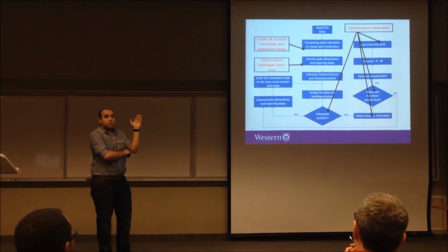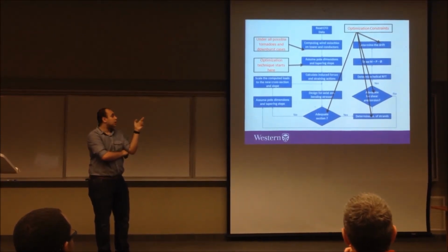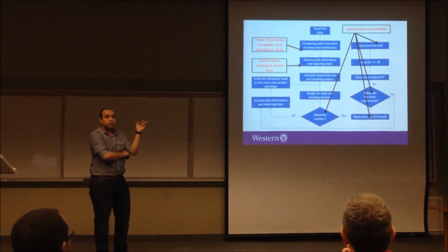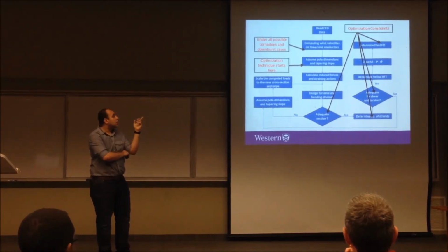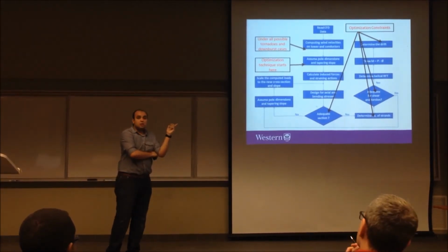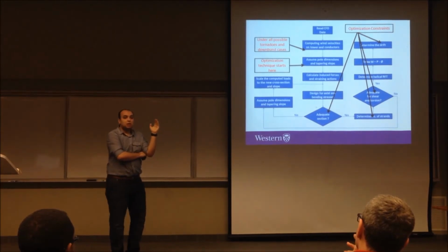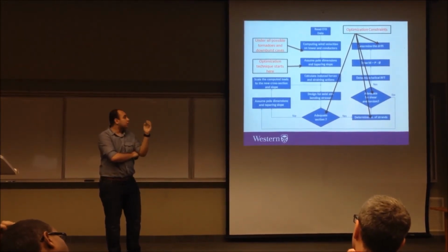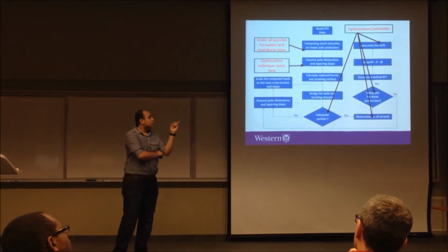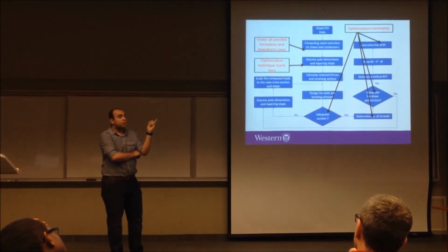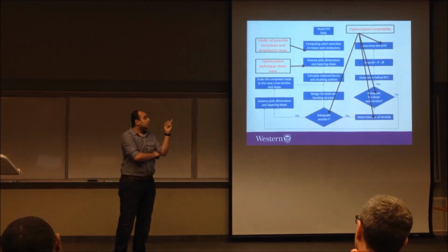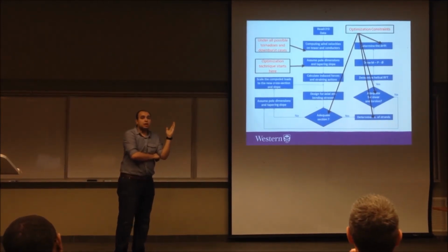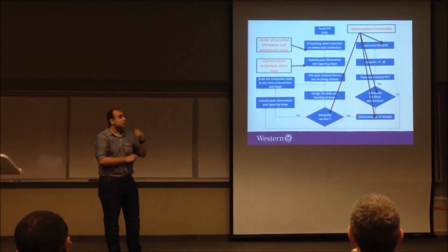There are some constraints in the optimization technique, like the adequacy of the section for resisting axial and bending stresses, and the number of strands, so that the minimum spacing shouldn't be less than the code recommendations. The adequacy for shear and torsion is also a constraint for the optimization technique, and the top drift should be within the allowable limit in the provisions.